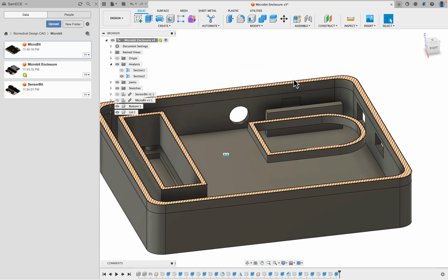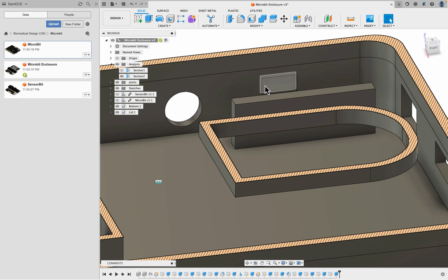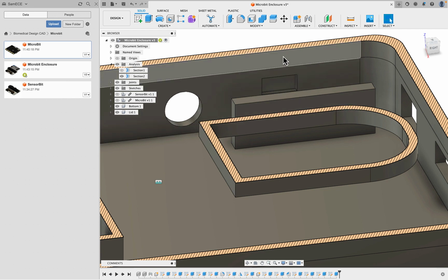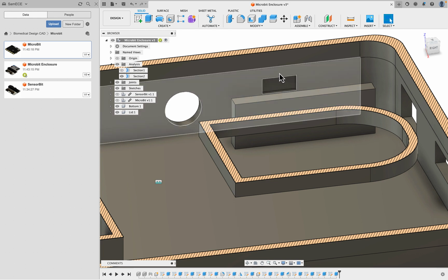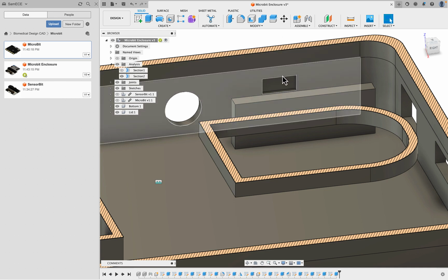So we would like a tab to be present from the very top of the lid, going down to this area here with a small protrusion. It should have a triangular appearance so that once it hits this surface, it'll automatically be pushed inwards. That also means that normally I would probably create this one to be located on this side, but actually I want a little bit of distance from the top to the bottom so it can sort of bend and snap into place.